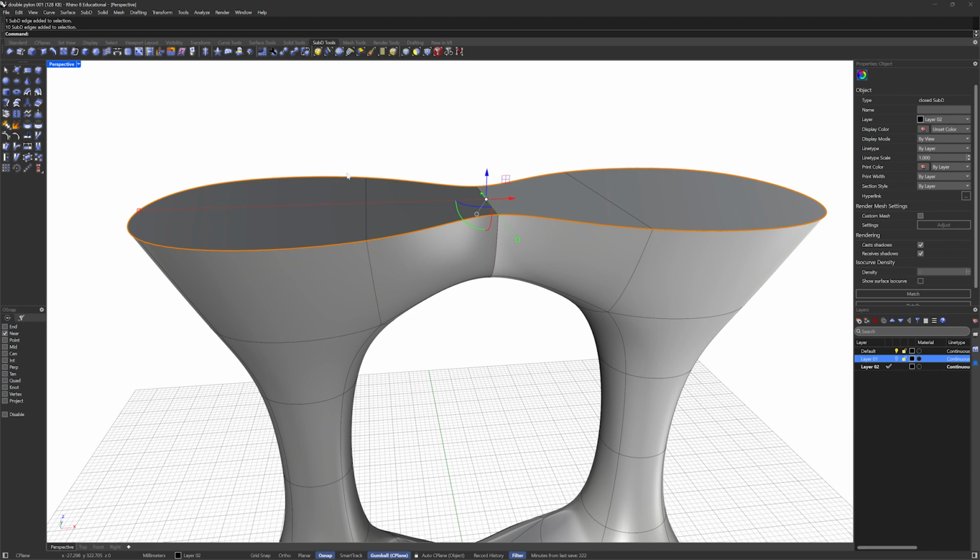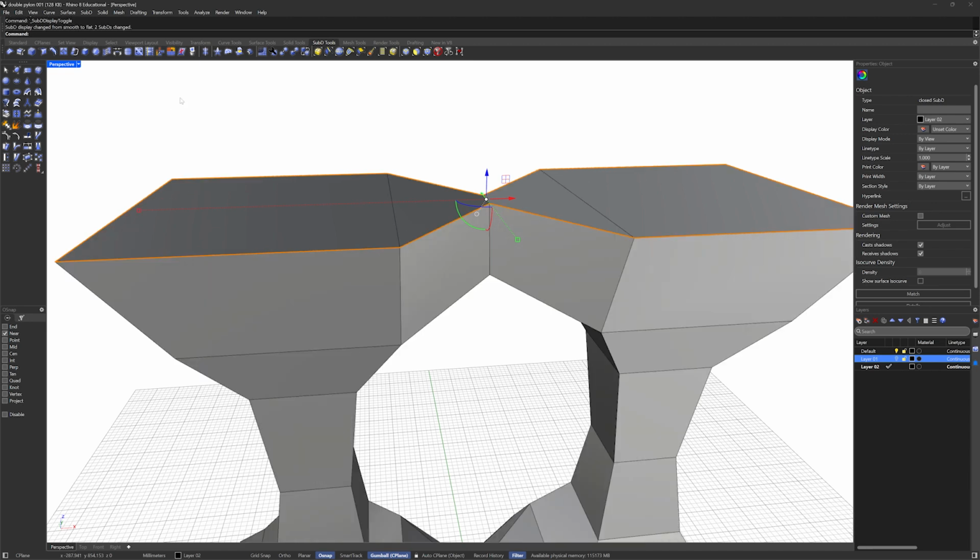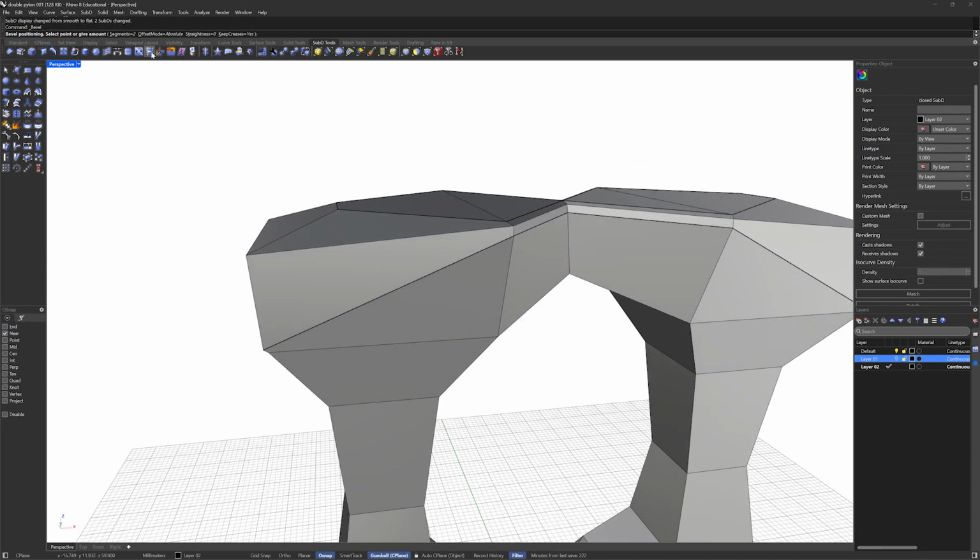The command I'm talking about is called Bevel. And this actually works way better in the box mode. So I'm going to switch back over. And here is Bevel on the top horizontal sub-D menu. And we have a couple options here. So we can vary the number of segments to add more detail or control.